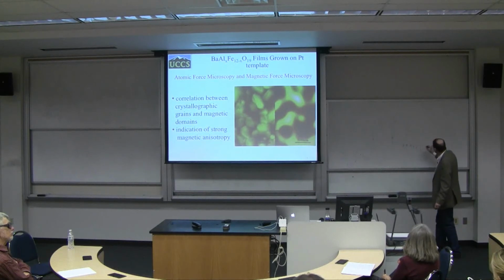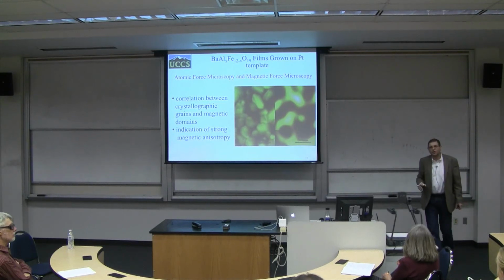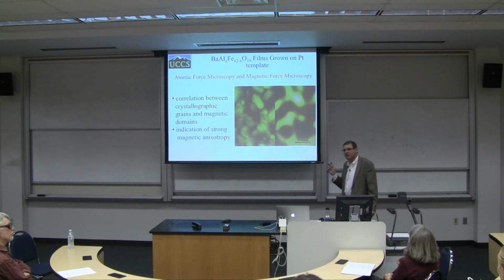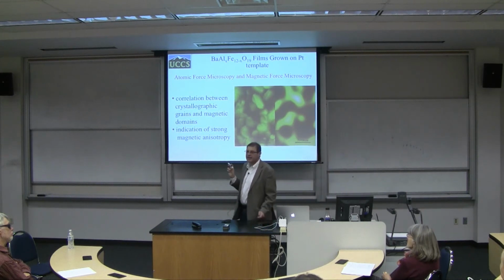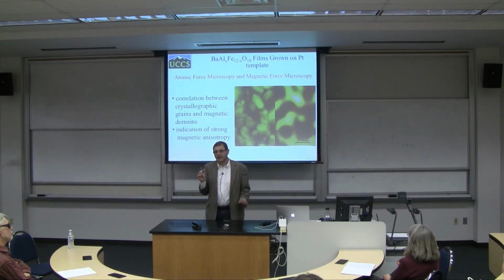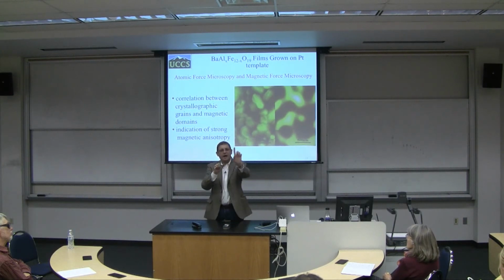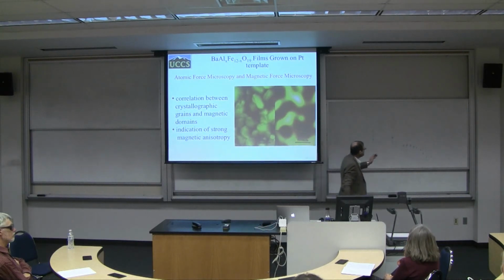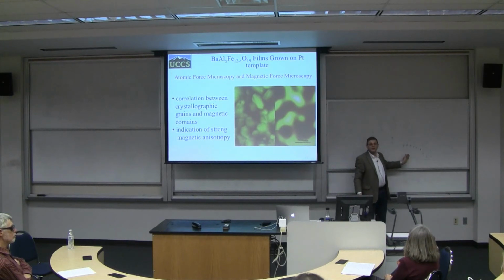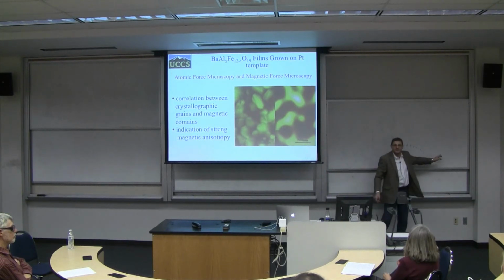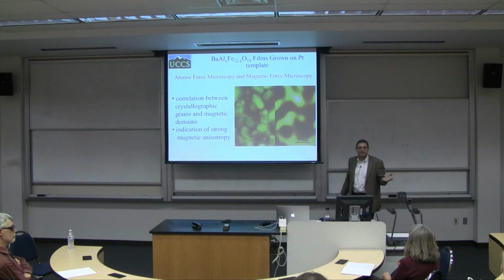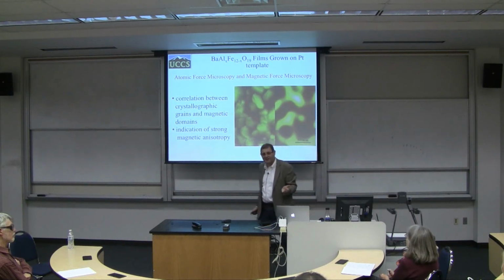And this region here, I call domain wall. Domain wall width is determined by how strong the anisotropy field is. In other words, if the anisotropy field is very strong, the domain wall will be very small. It will go from one orientation to another. In a material like iron, I need about 1,000 angstrom, so 500 atoms, to go from one orientation to another. Therefore, iron is a soft material, anisotropies are small.